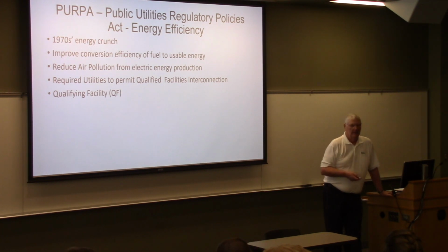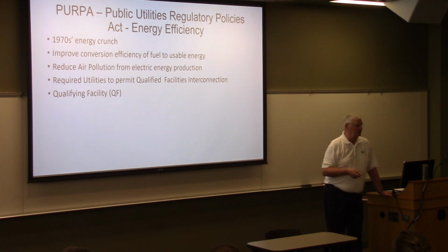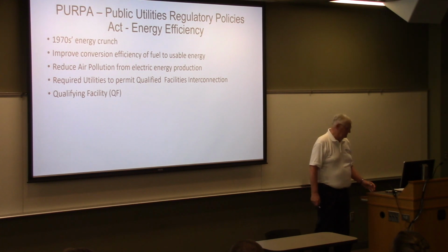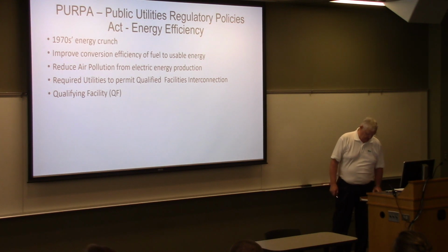Well, an owner of a building can put in a combined heat and power system where he takes the heat off of the prime mover and uses it to produce hot water or steam. A lot of hospitals do this because they have a tremendous need for hot water. And you can get heat from a prime mover to heat water for your domestic needs very cost effectively. In fact, some of their efficiencies will run as high as 72, 73% of fuel to energy conversion in that CHP plant. So it's a very cost-effective way to meet your energy needs, particularly if you have a high need for energy.